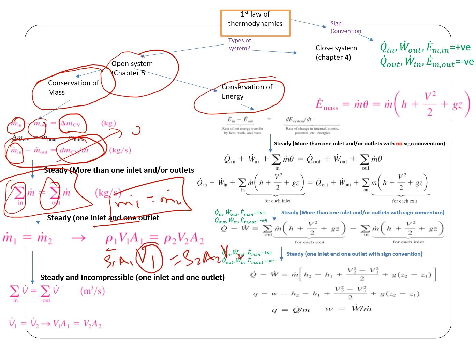The most important thing is how the main equation simplifies to this equation based on assumptions. So whenever you solve a problem, the assumptions are very important. Sometimes some of the assumptions may be explicit, and sometimes they may be implicit. For instance, if it says copper, then you have to assume that it's a solid, it is incompressible. So density 1 equals density 2.